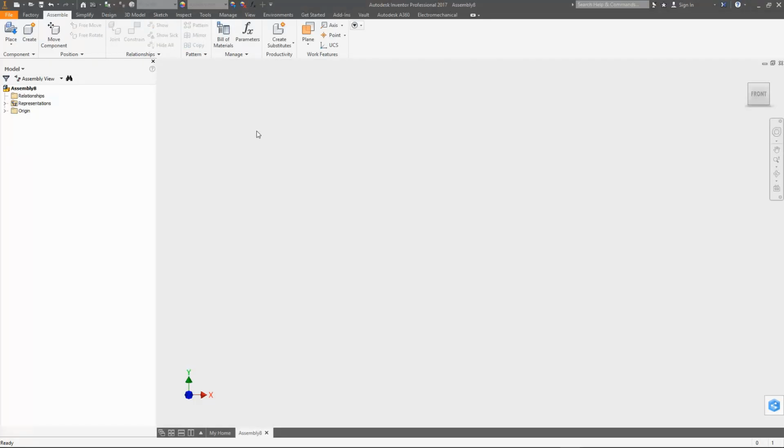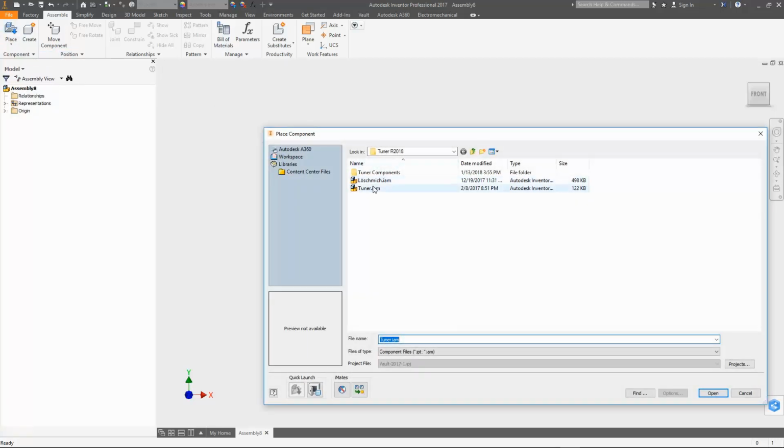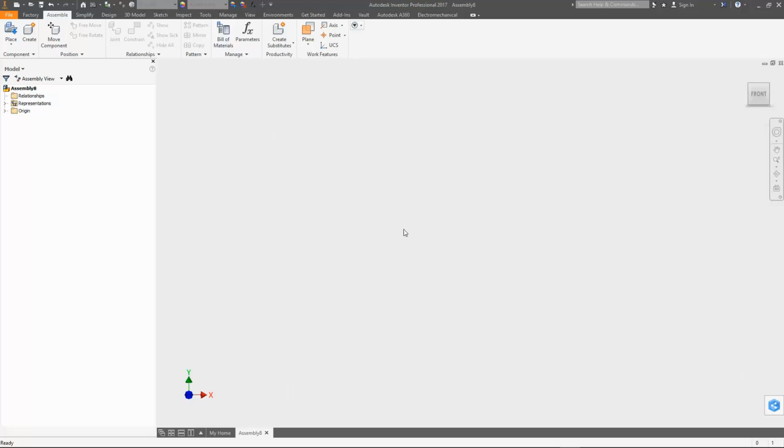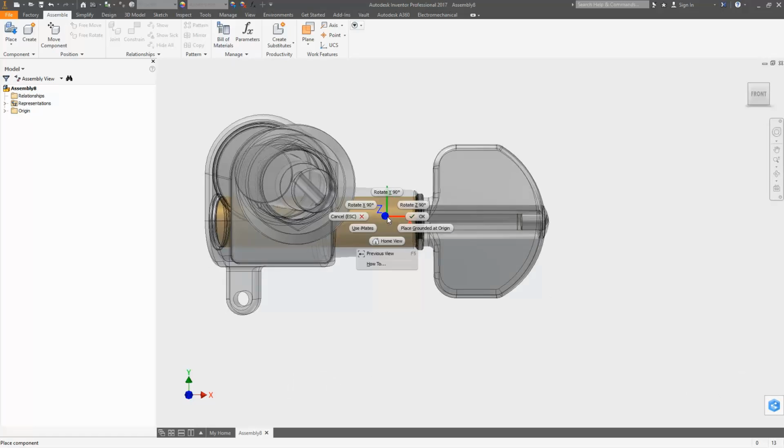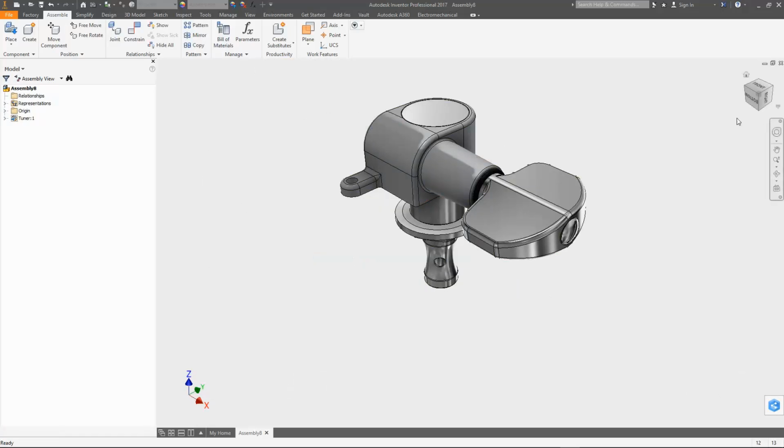Alright, again a closer look at Inventor and the enhanced AnyCAD functionality. I think a quite often required use case is to reference datasets from newer Inventor versions in assemblies. There is no need to use an additional command. You can use the Place Component command. Focus on the displayed Inventor version, please. The dataset has been created in release 2018. Further, you can work with future datasets as usual.